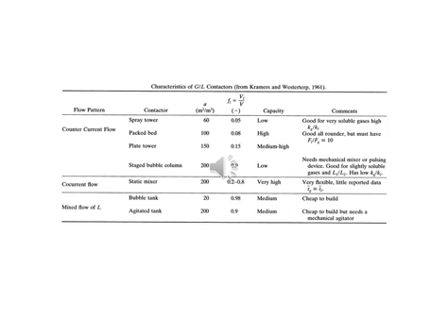While for very high interfacial area, we have countercurrent flow, static mixers, and agitated tank and bubble tank. For a system that has a high FL, we have the tanks, the bubble tank and the agitated tank. While for systems which have very high FG, we have spray tower, packed bed, and the plate tower.